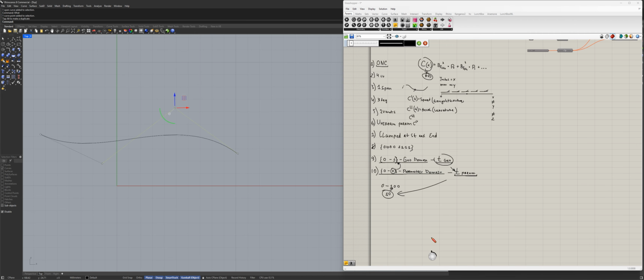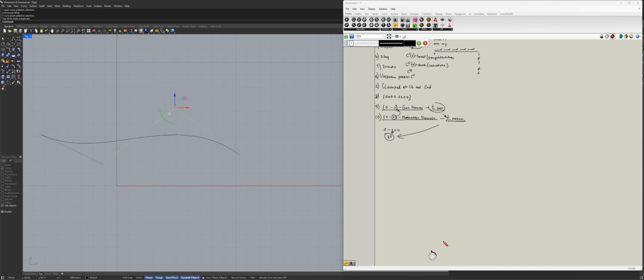And actually, before we talk about the surfaces, let's look at how it works in practice and what all of this gives us. And to do that, in Grasshopper, first, I need to bring this curve into the Grasshopper. How am I going to do that? Well, I use some nodes, which basically give me an ability to take this curve and toss it into the Grasshopper so I can operate with that. The problem is that Grasshopper doesn't hold geometry. It can't do that. All the geometry is in Rhino. It's not in Grasshopper. Grasshopper can only stream.